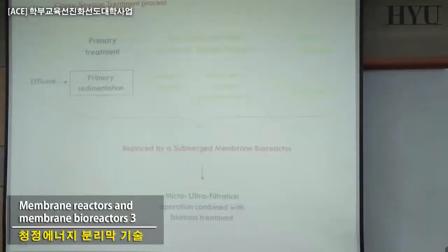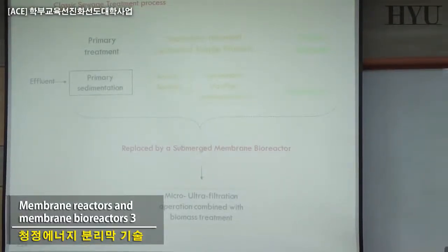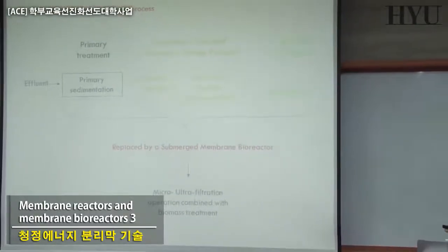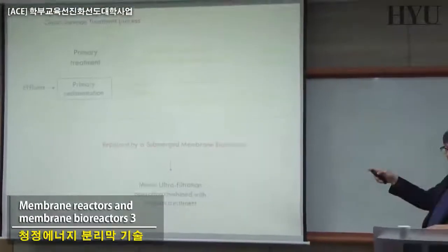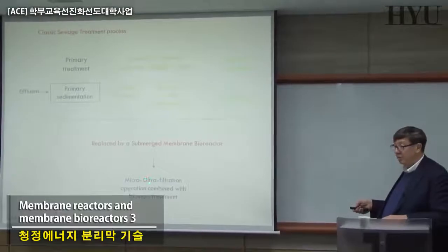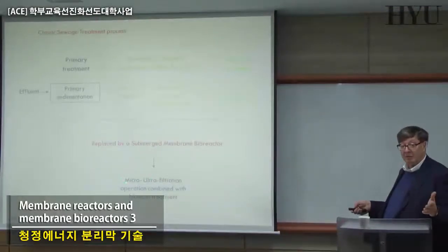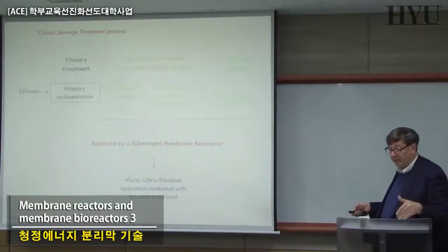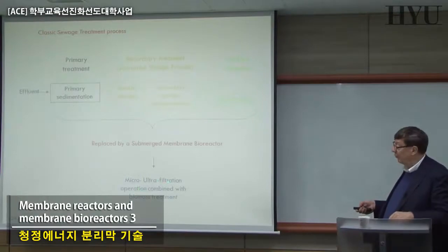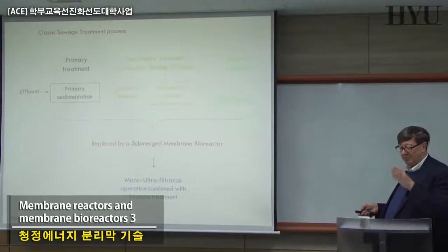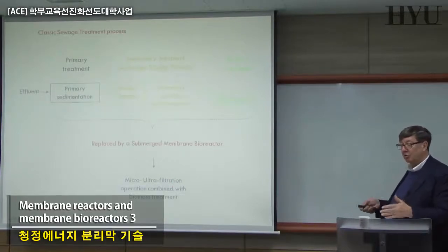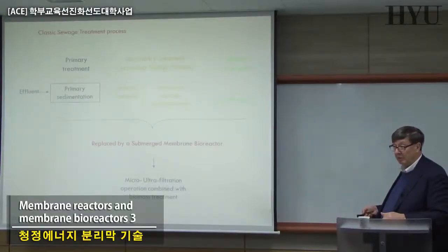It's not so anymore. This can be membrane distillation. That can be nanofiltration, depending on which kind of separation you want to obtain. If you want to be more sophisticated than what is here, you can just change here, and you can introduce any kind of membrane operation. Particularly if you go a little on the web, you will find already MD or nanofiltration, a much more severe separation and control of the quality of the permeate that you must have.